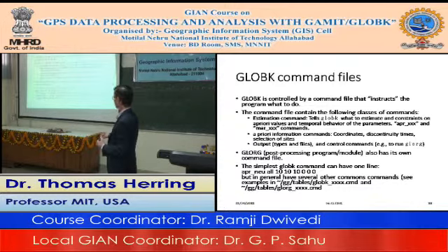It'll have large coordinate uncertainties because nobody's particularly constrained here. But if you look at the separation between the sites and the baseline lengths, you'd find those are well determined. And there's an output option you could add to this to get that output if you wish. In general, you have several more commands than this, and we'll look at those examples in the GLOBK templates that we supply with the solution.